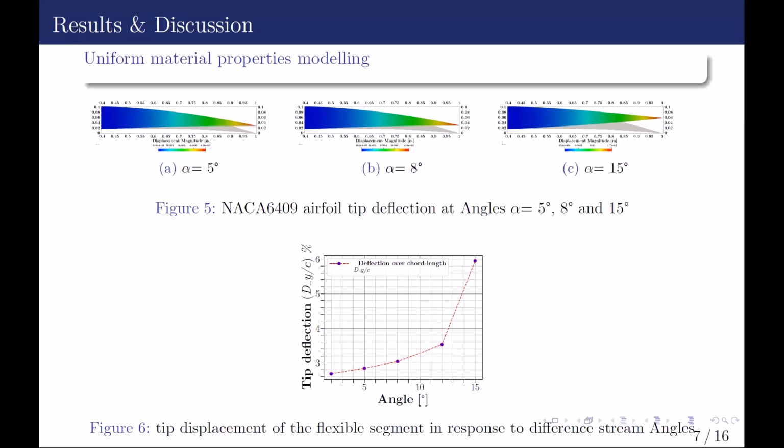That is, at low angles of attack, we can see in this figure that the deformation is quite linear. But with increasing angle of attack, we find there is a nonlinear regime in which the deformation is quite exponential by increasing the angle of attack further, after 12 or 15. From an aerodynamics perspective, we can give the reason for this as what we call the separation problem in the CFD prediction. By increasing the angle of attack, we will have a problem of separation, and even the solver sometimes has difficulties to predict this separation, what we call the laminar separation bubble.